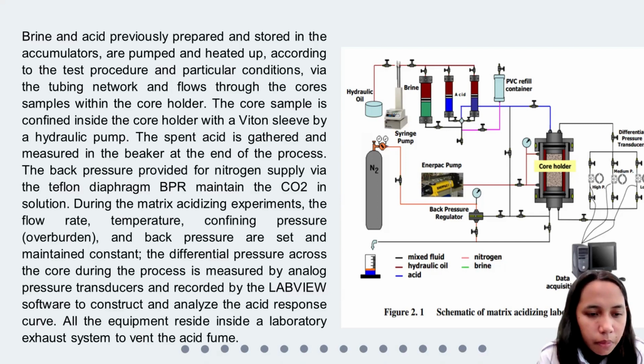The back pressure provided by nitrogen supply via the Teflon diaphragm BPR maintains the CO2 in solution. During the matrix acidizing experiment, the flow rate, temperature, confining pressure or overburden, and back pressure are maintained constant.